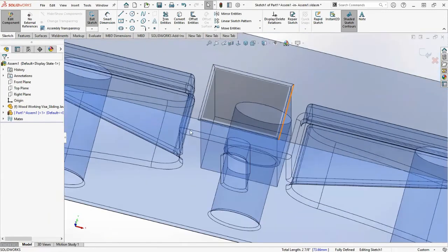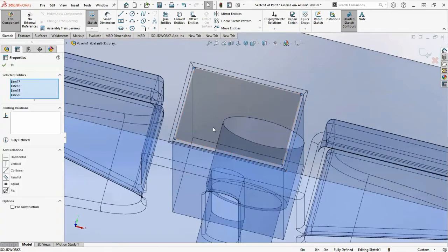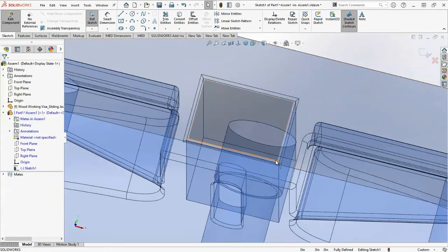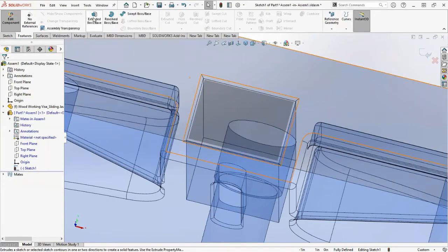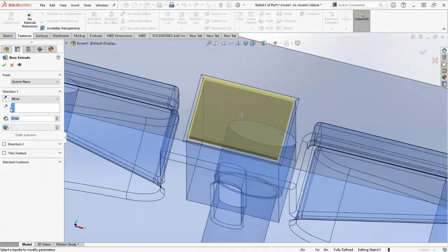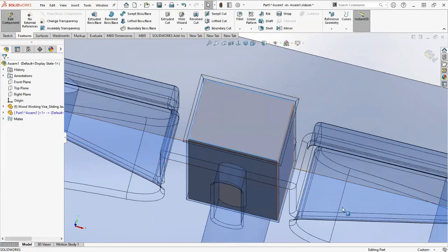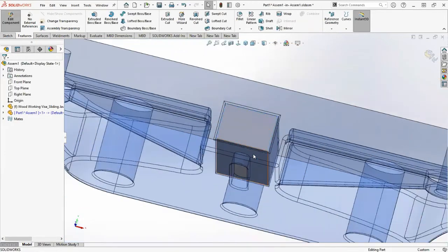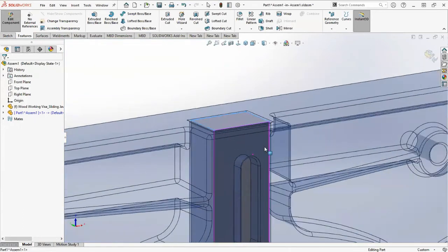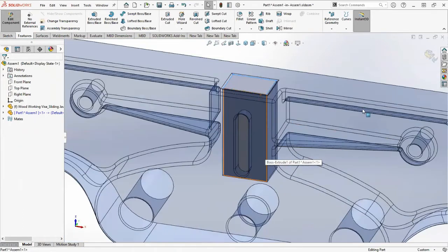And you can see now I've got my part profile there. It should be showing black lines around this, but sometimes graphics can be a little funny in SOLIDWORKS, but it's there. So now I'll go into features and extrude that in the other direction by 1.775 inches. All right, and I can see that I've created that vice dog, or at least created the majority of it.